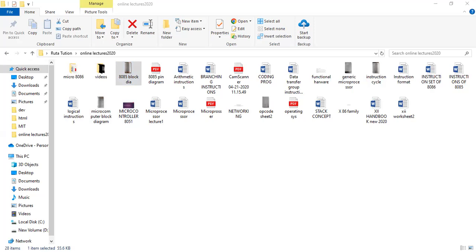So register names, you know, B, C, D, E, H, L, stack pointer and program counter. Then you have the incrementer and decrementer latch, so that will increment and decrement the addresses. The address is 16-bit, A0 to A15. Out of that, AD0 to AD7, that is the lower 8 bits of the address, is multiplexed with the data. So here if you see, it is a data address buffer, which gives AD0 to AD7. Data is bidirectional, therefore this arrow is bidirectional.